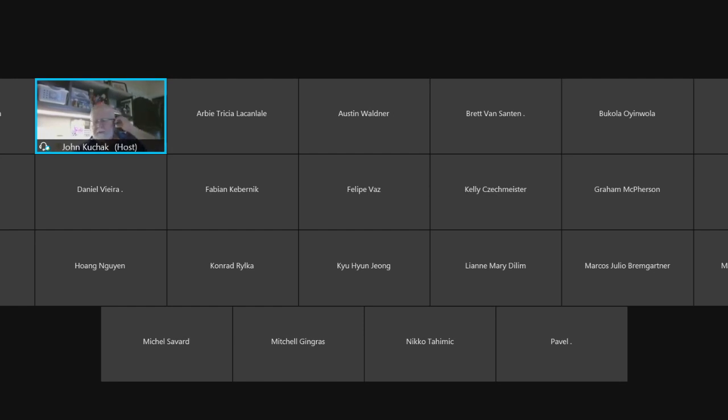So any of you that may have worked in the industry and were testing concrete, and the city spec calls for 32 MPa, the ready-mix producers' mix design has to be such that they should be breaking around 37, 38 MPa. If they're not, they're going to fail. One test in every 100 almost is going to fail. That's just the way it is, statistics. So you do not design for exactly 32 MPa because chances are you're going to fail it most of the time.